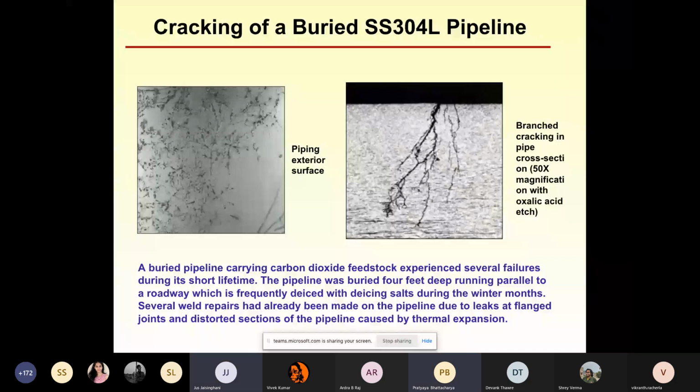The melted water percolates through the soil. So basically salt dissolves in water, and it seeps in through the soil, comes to the pipes, and it is corroding the pipes. Now, as I told you, you need to have two things in play for cracking to happen. One is this business of reduction in strength of the material, and second is internal stresses.